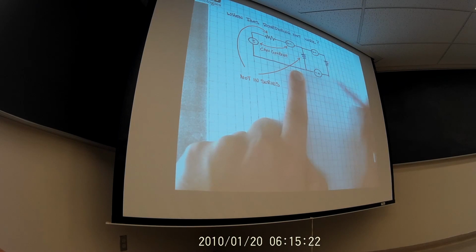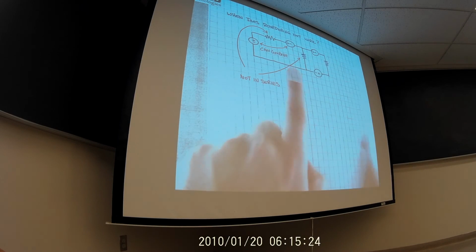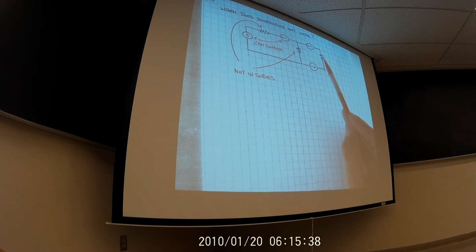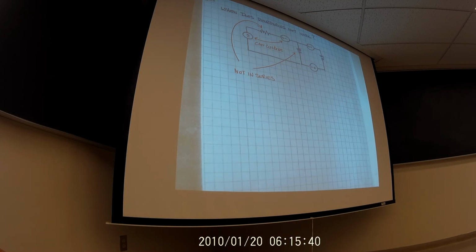And so we might have even bigger ones with more boxes moving outward. So what we would do is simplification, simplification, simplification in order to solve for the current through that one loop. And then fortunately, when you want to get, let's say, the voltage across this resistor, you have to do expansion, expansion, expansion. But at least you're starting with a value that's known. So you solve for that.